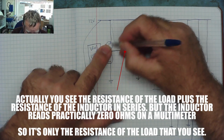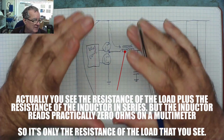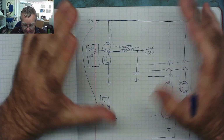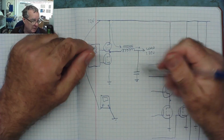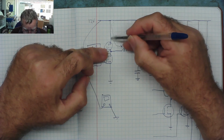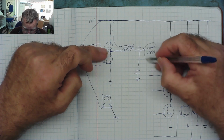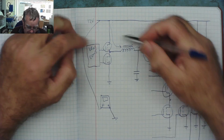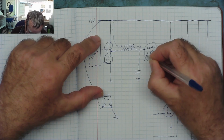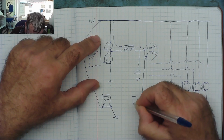Because if there's a short here, the current is flowing through the short. I mean, when I say current, your resistance meter injects a small voltage to measure the resistance, and it measures the resistance by working out how much current is flowing. So the test meter does send current into the circuit. The current flows through the short circuit MOSFET, through the coil, charges up these capacitors, and you see the resistance of the load. It's exactly the same thing as if you connected your test meter, and it would make sense if you connect one end to the coil, and you're connecting the other end to ground.